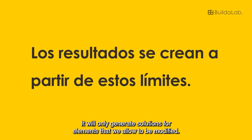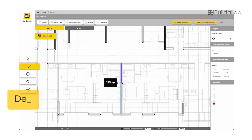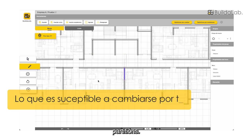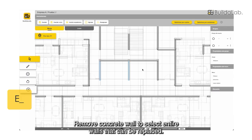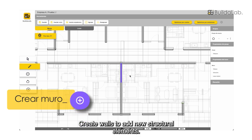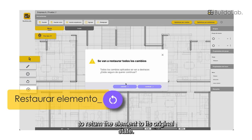It will only generate solutions for elements that we allow to be modified. For the walls we have several options. Delimit allows us to indicate which sections of a wall can be replaced by partitions. Remove concrete wall to select entire walls that can be replaced. Create walls to add new structural elements. Restore to return the element to its original state.